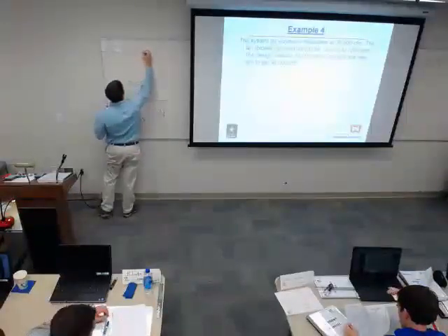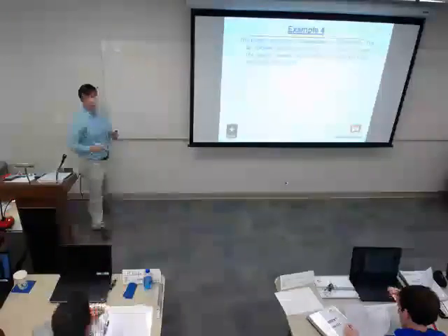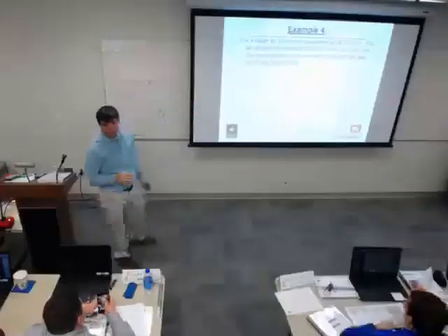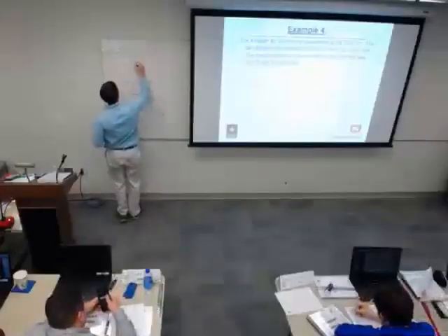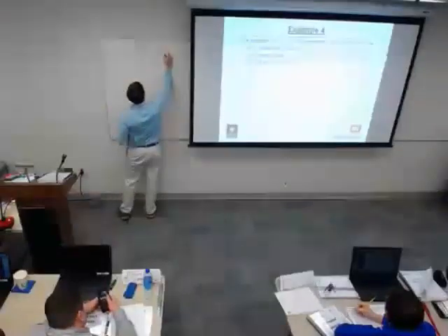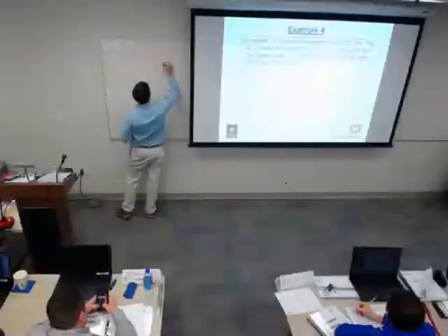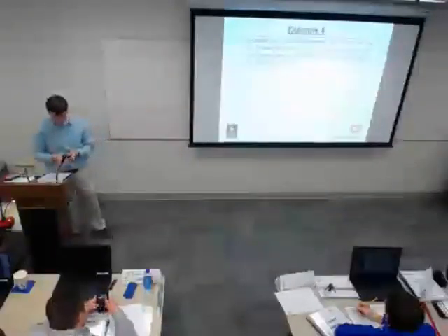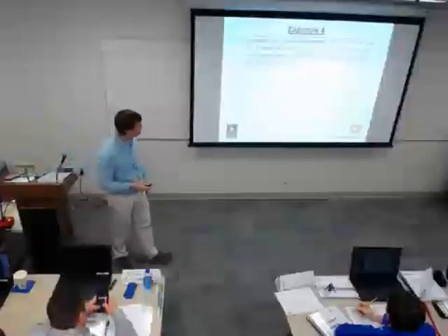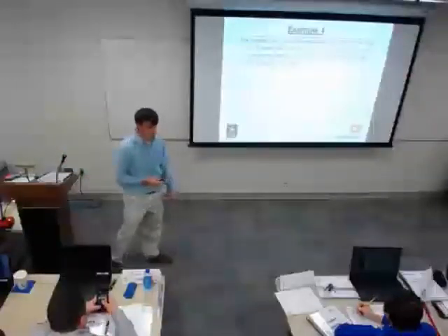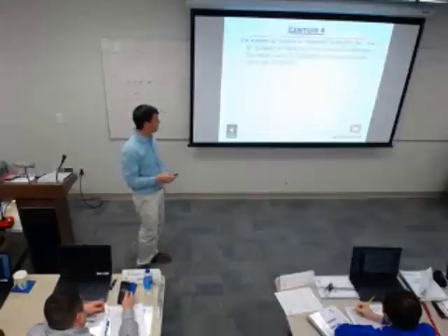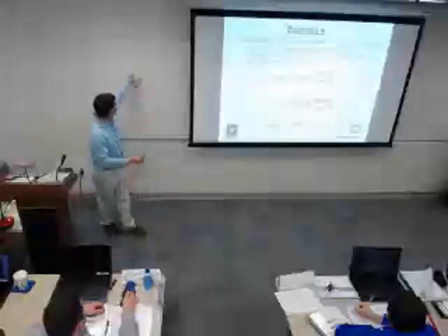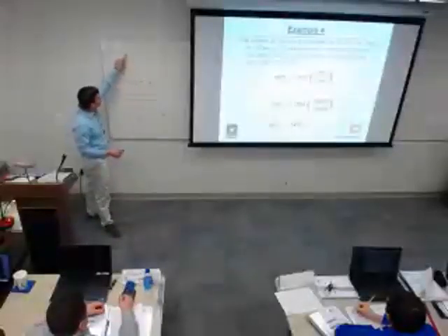We're trying to get to RPM2. I gave you CFM2. The design called for 34,000, and you got 30,000. Anybody got a number that they want to share? Sounds right, 1417.